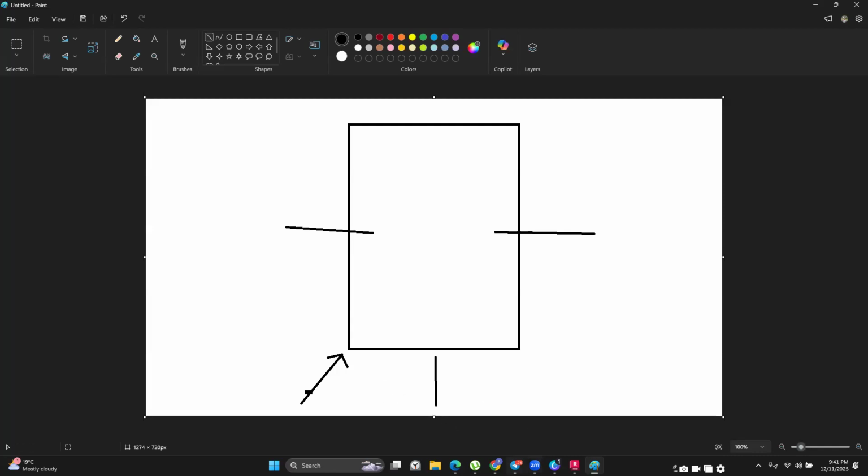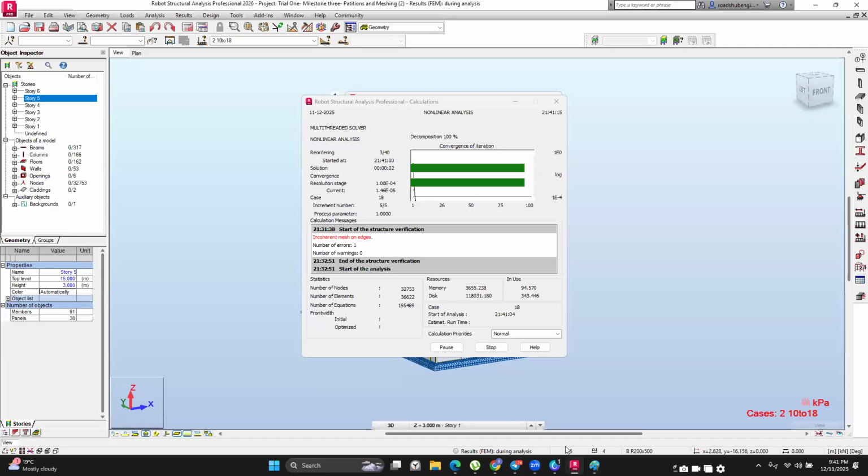No, okay. Yeah, just to categorically state that whenever you are considering wind loads, you consider them in one direction, where the highest wind is expected. Usually how you determine this is the location of the structure vis-a-vis where wind is coming from.